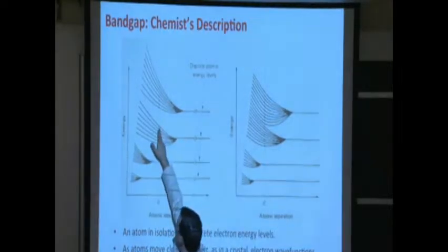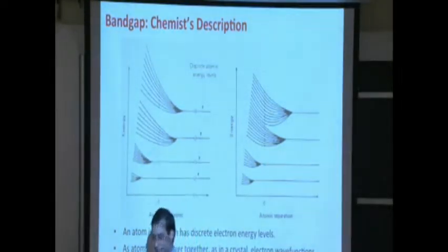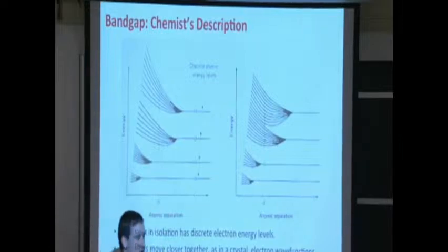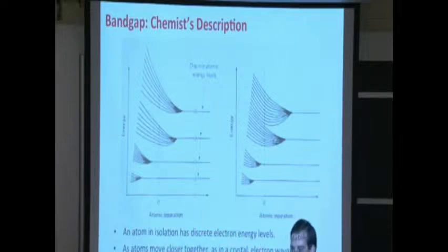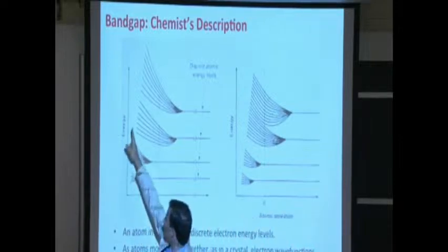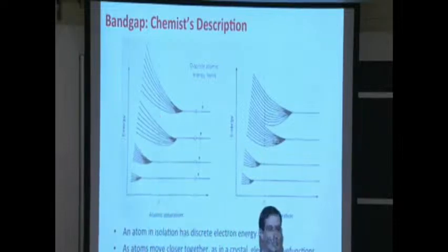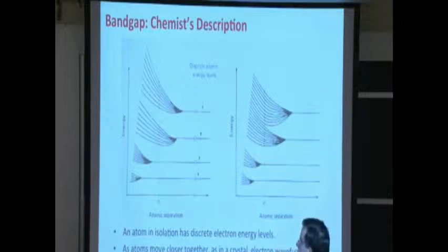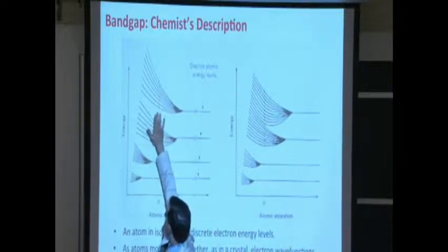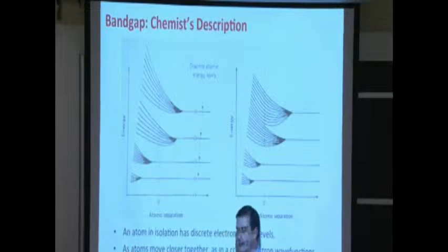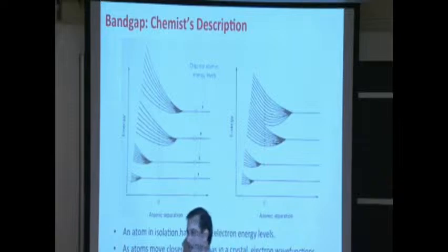And this gap right here is an interesting thing. There is no stable electron orbital. If you were somehow to take an electron with that given energy, this energy here, from the vacuum and stick it inside of the system here, it would quickly decay into a stable orbital. So this is a prohibited band of states. There is no stable orbital for that electron to exist at that energy, and hence we call it a band gap. The reason band gaps are interesting is because different materials have different, or can have different size band gaps.